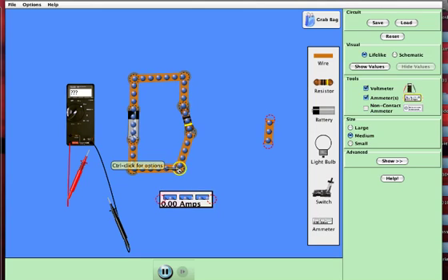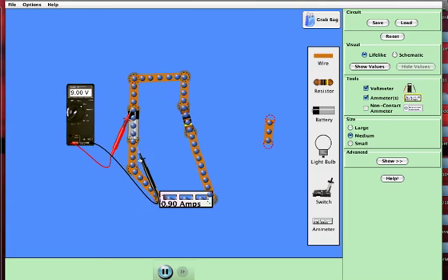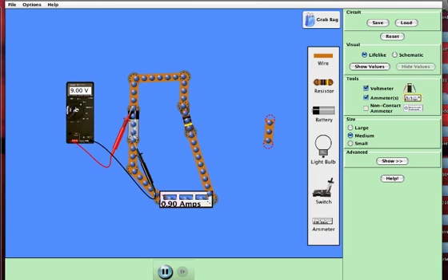I'm going to split this junction, is you need to have it set into the wire so that the current passes through it. With a voltage, and this is the voltage meter over here, you need to measure the potential difference between two places. And on the dials that we'll use, there'll be different settings on the actual meter that we'll go through and use.